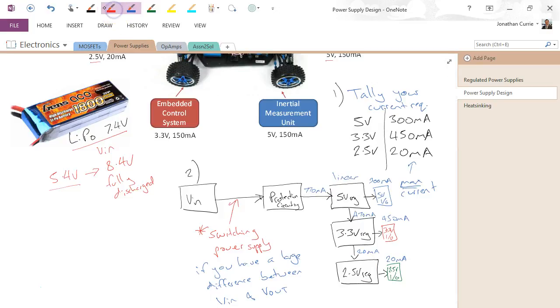In reality, I normally uprate my design. I would say this one for, let's say, 30 milliamps, and therefore I would uprate this one to probably at least 550, and then this regulator probably to 800 or so. In fact, probably a little higher, maybe 900. Okay, so these numbers are with a buffer, just to over design this application rather than undesign it. Design it for the worst case scenario.